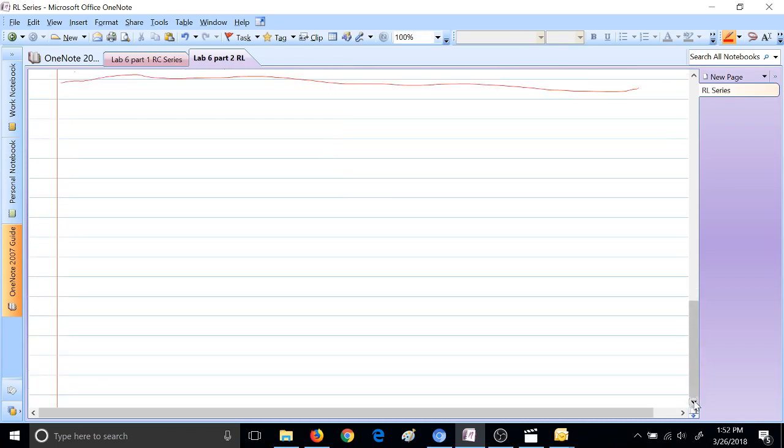You're going to do the same thing for each component, and then you're going to add the capacitive and the inductive reactance parts. And remember, they're going in 90 degrees in opposite directions, so the only difference is one's going to be negative, one's going to be positive, and you're going to get a resultant. So part one, and the last part, is find the total impedance, sort of like what we did here. This is just going to be a little bit more involved. Find total impedance.